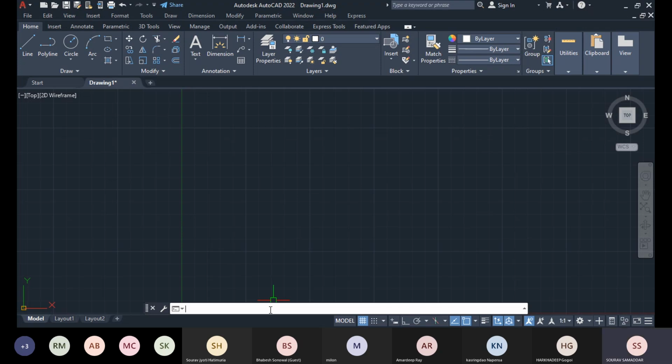So we have two basic and primary pages. The first one is ACAD ISO.dwt, which is also known as the metric page, or the millimeter page. The dimension of the page is 420 by 297, that is a standard A3 sheet.